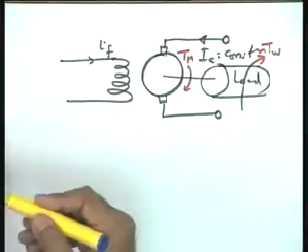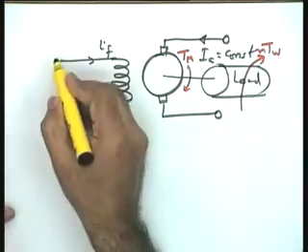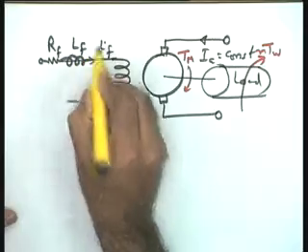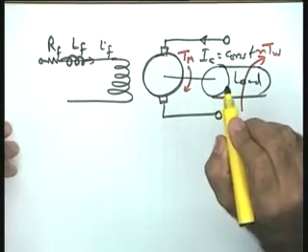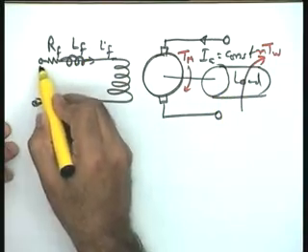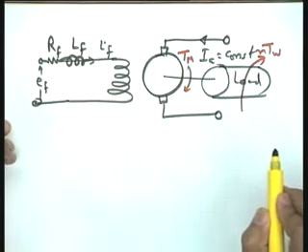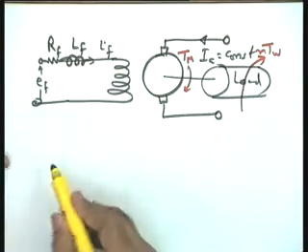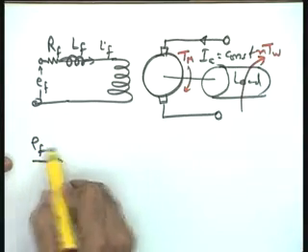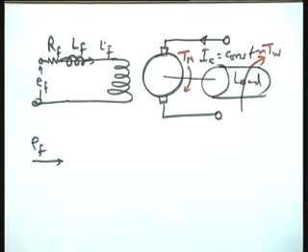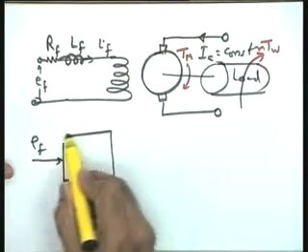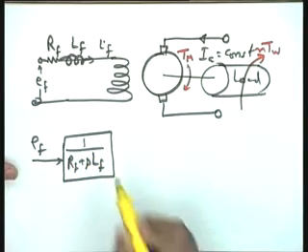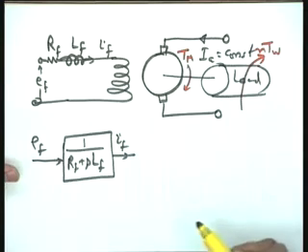Okay? So, in this particular case, the armature resistance, the field resistance and field inductance, both the parameters I am taking, because the field inductance is not negligible. Both the parameters are being taken and EF is the voltage which is the controlling voltage which controls the torque. So, let me make a diagram. EF is the variable here, there is no back EMF facing EF. So, I can put a block directly, that block is 1 over RF plus SLF. This gives me IF, the field current here.